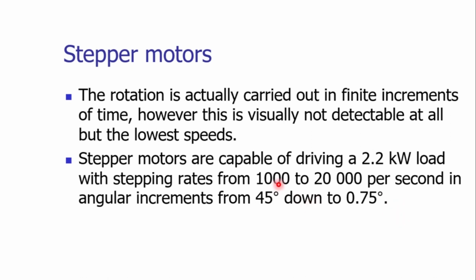In general, we can have stepping rates varying from around 1000 to 20,000 per second, and we can have angular increments from about 45 degrees down to 0.75 degrees.